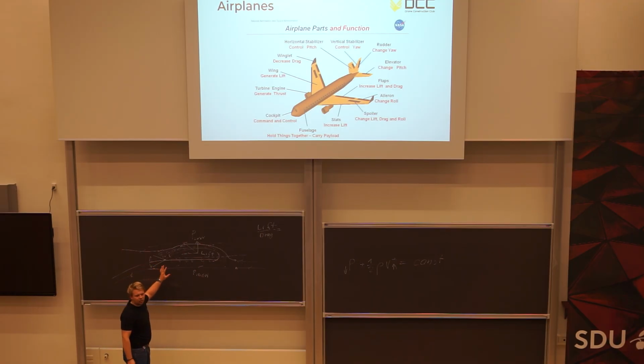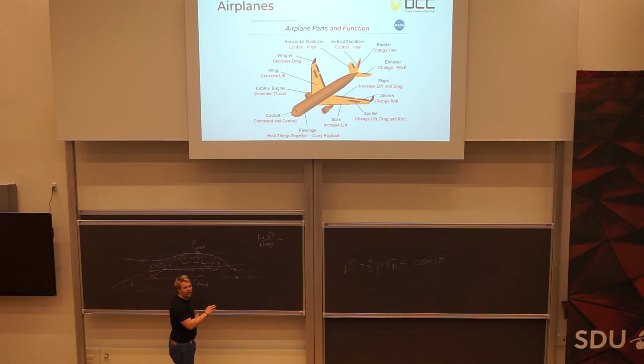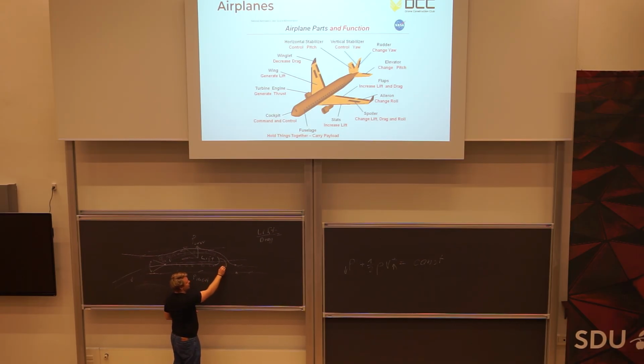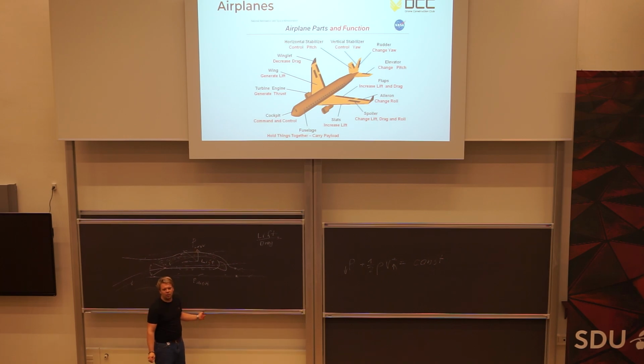But what I wanted to show you in particular is you can also change the geometry of the wing in many different areas. You can see on most airplanes nowadays, bigger ones, you also have slats. They are in front. This usually extends the wing's length, which also increases the lift, but increases the drag.